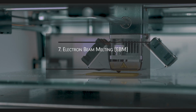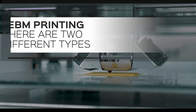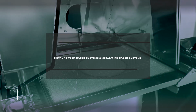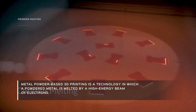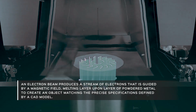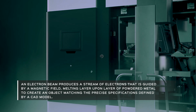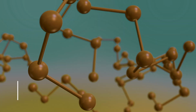Electron beam melting, or EBM. There are two different types of EBM printing: metal powder-based systems and metal wire-based systems. Metal powder-based systems 3D printing is a technology in which a powdered metal is melted by a high-energy beam of electrons. An electron beam produces a stream of electrons that is guided by a magnetic field, melting layer upon layer of powdered metal to create an object matching the precise specifications defined by a CAD model.